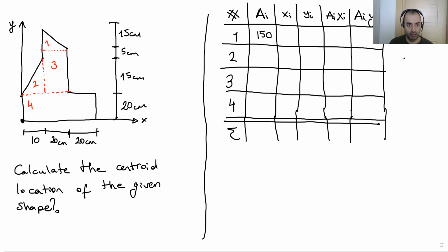Let me change the color, orange. So xi, remember, we have a triangle. We are gonna use the 1/3 rule to find its center. Actually, its center is gonna be around here, right? So this part is 1. This portion is 2. Actually this part proportional with 1, this part proportional with 2, totally 3. So what we have here, 20 over 3.